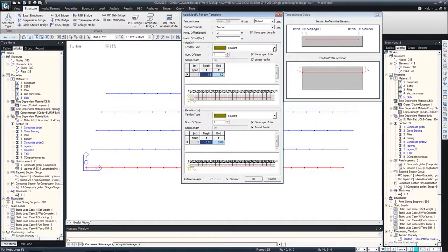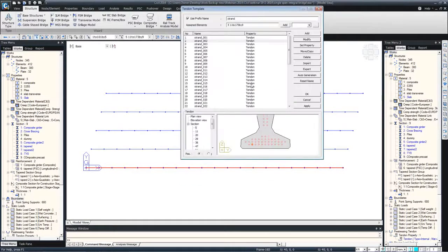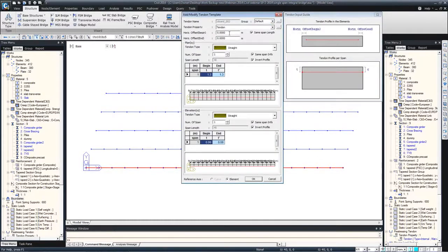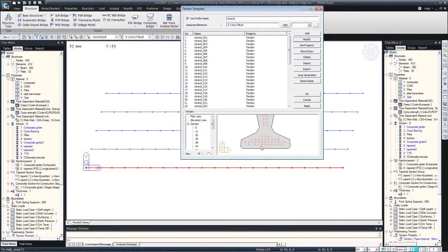And you can go for a varied number of shapes. So for engineers who are using midas for post-tension box girder sections, this particular wizard can be used very easily for the parabolic tendons and for other types of draped tendon profiles, something like this. So in this example, we'll focus on straight only, and just cancel and reselect that again. Yes, so that's 2 meters and 2 meters here. Span length is auto calculated, so click OK, and that tendon is now debonded.